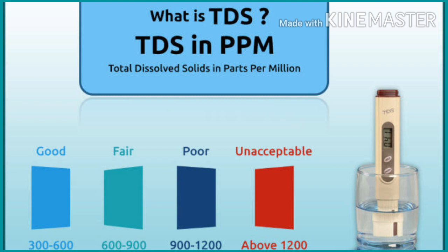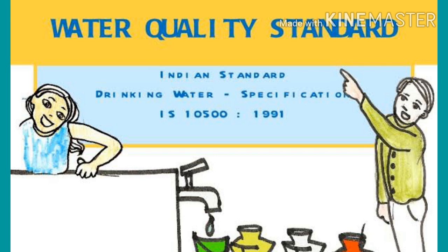It is recommended that the acceptable limit be implemented; values in excess of those mentioned under the acceptable limit render the water not suitable. Such a value may however be tolerated in the absence of an alternate source. Pesticide residue limits and test methods are also revised, and routine surveillance of drinking water supplies is also given as per WHO guidelines.